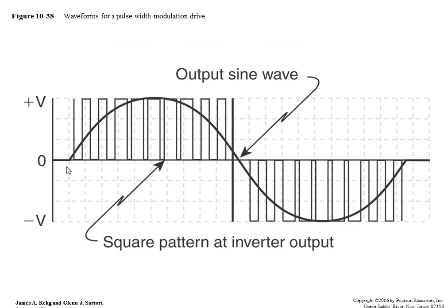So now this is a pattern. I'm on a little bit, so I get a little bit. I'm on a little bit more, I get a little bit more. I'm on a whole lot. Now I've got higher voltage. So I'm doing a pulse width modulation of the signal to simulate an AC signal. That's what I'm going to do. And now I can change the speed because I can change the speed of my pulse modulation.